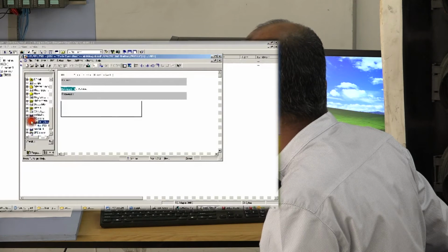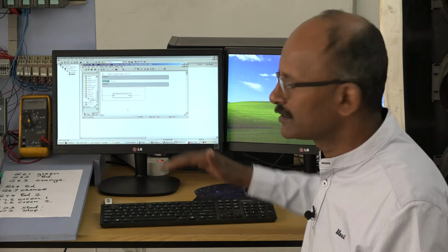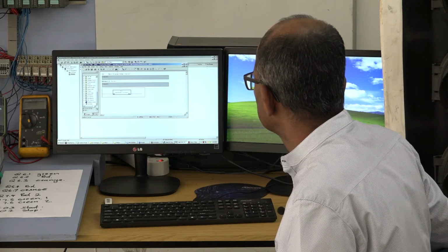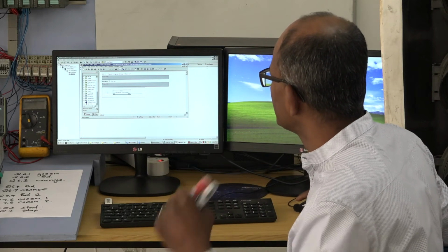when you're running, please only use FC1, which is the latching circuit. So I've now programmed that in there. I can now save that. Okay, I will download that to the PLC. I've now sent it through.